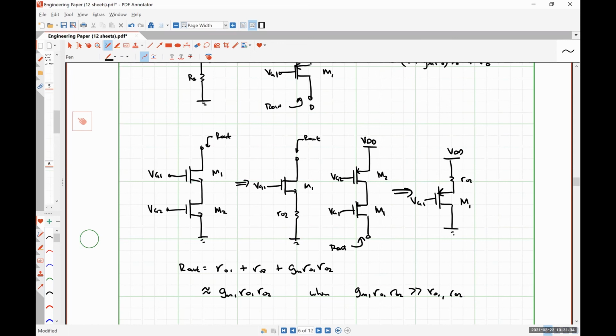Just like in BJTs, we can treat transistor 2 as the one that is establishing our operating point, and then we're simply loading it with another high impedance transistor, which is causing our output gain to boost. Again, it's the exact same concept as before, no big deal.